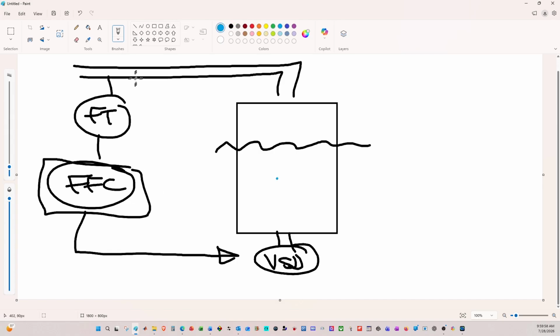Can you see what's happening over here? I am measuring the flow in order to control the level. So I'm measuring one thing to control something else. If the flow increases, I will run the variable speed drive faster to pull the level down. If the flow decreases, I will run the variable speed drive slower so that we're not going to deviate too much from the level. In this case, again, we're being proactive. We're measuring one thing, and we're going to control something else.